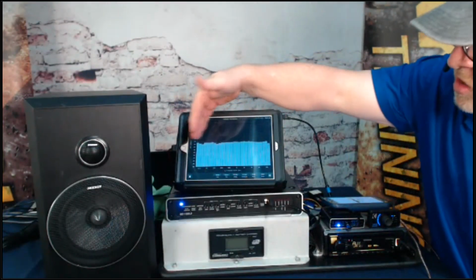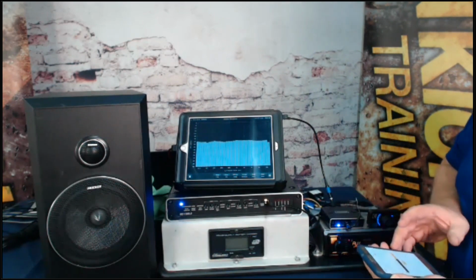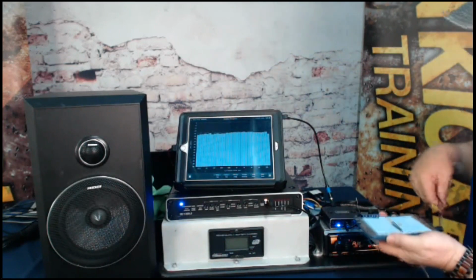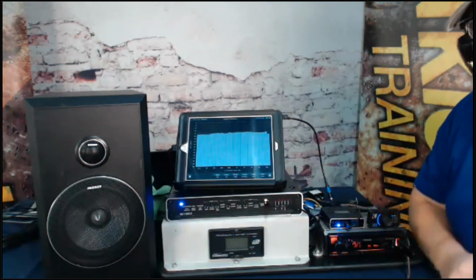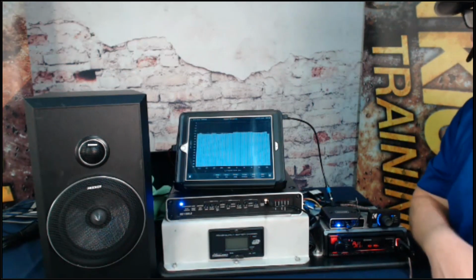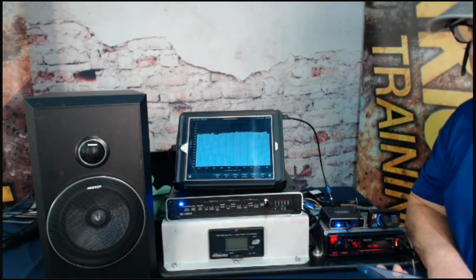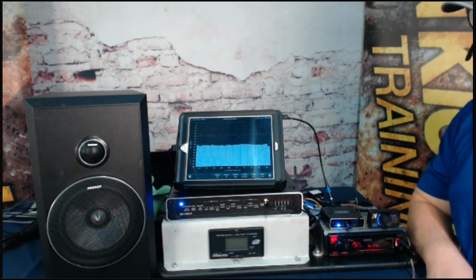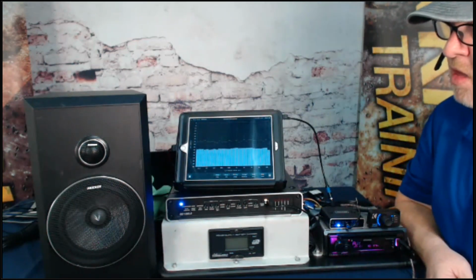I've got equal amounts of all frequencies. As I turn the volume up and down, you notice it stays very consistent, and that's coming right out of the headphone jack of the phone. There's a little roll off here at 20K. That's actually the filters in this iPad, but that's still a very usable, very good signal. As I turn the volume back down, it's still a flat frequency response. Now, if I go all the way down,